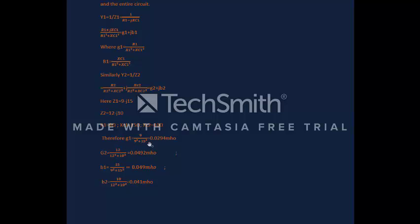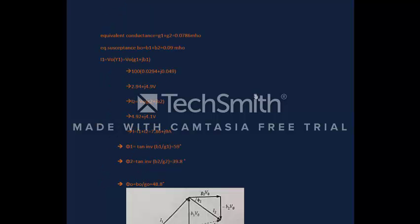Therefore, G1 turns out to be, by calculating, 0.029 mho, and G2 will be 0.424292 mho. B1 is equal to 0.051 mho. B2 is equal to 0.05141 mho. Equivalent conductance is equal to G1 plus G2, and equivalent susceptance B0 is equal to B1 plus B2.